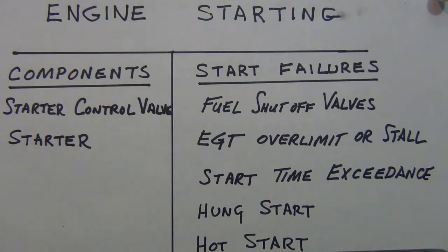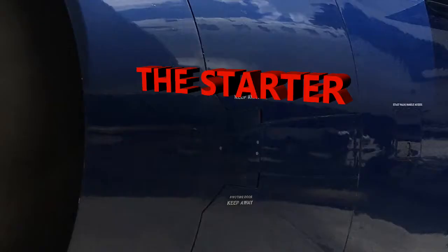Just an added piece of information. It's not critical for you to absolutely memorize, but just know the starter valve has 2 pneumatic actuators in it. Depending on the sizes of valves, you may have 1, 2 or 3 actuators. This one in particular has 2. Okay, so that's just your air starter control valve, providing air to the starter, which is connected to the engine, so you have that connection, that transfer of energy to get the engines spooled up.